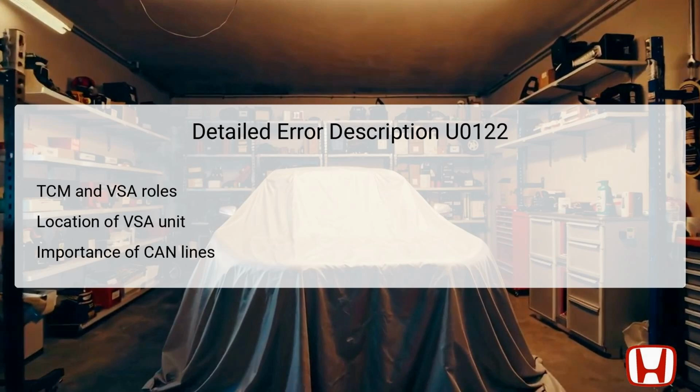These control modules rely on the Controller Area Network, CAN, to communicate. The CAN employs two lines, FCAN-H for high-speed communication and FCAN-L for low-speed data. If this communication is disrupted, it leads to DTC U0122. For example, if the TCM does not receive any information from the VSA Modulator Control Unit for a period longer than 1.5 seconds, a malfunction is detected, leading to the specific error code being logged.